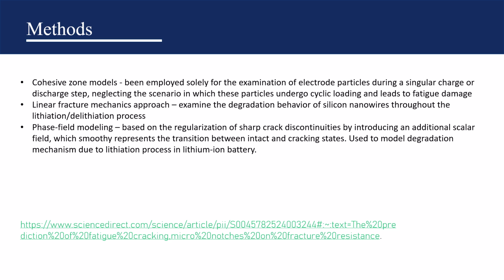So the first method is cohesive zone models, which have been employed solely for the examination of electrode particles during a singular charge or discharge step. However, it neglects the scenario in which these particles undergo cyclic loading and leads to fatigue damage. The other method is linear fracture mechanics approach, which examines the degradation behavior of silicon nanowires throughout the lithiation and delithiation process. And then the final method is phase field modeling, based on the regularization of sharp crack discontinuities by introducing an additional scale field, which smoothly represents the transition between intact and cracking state.